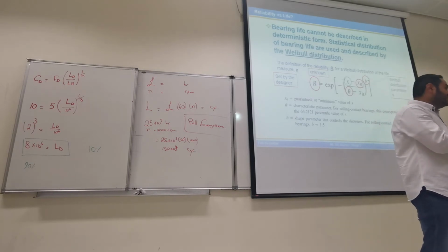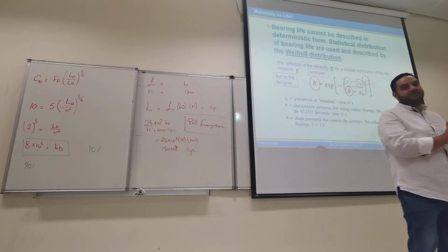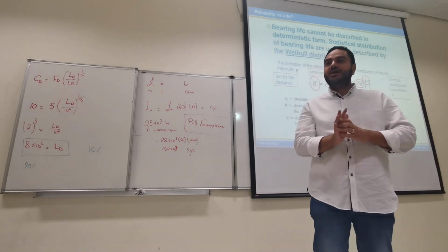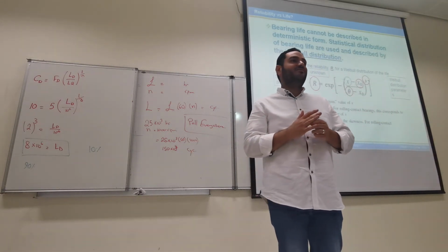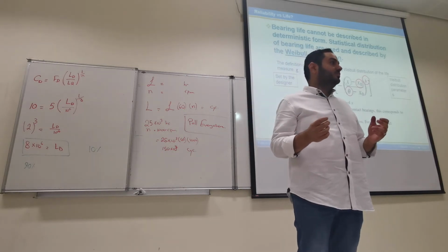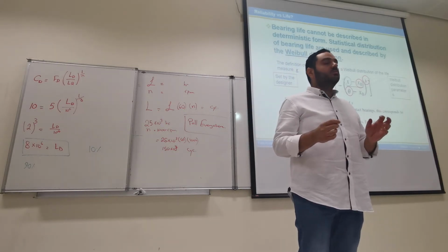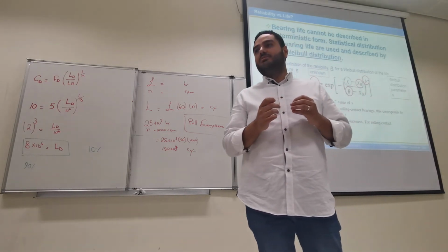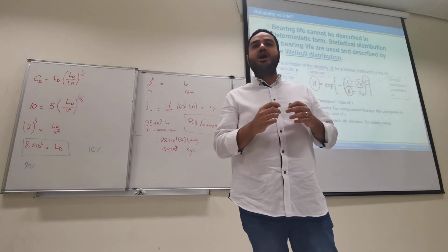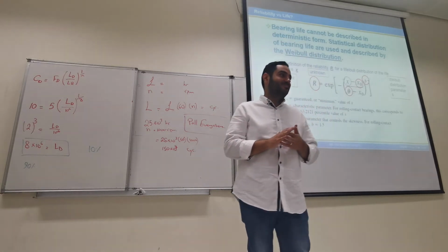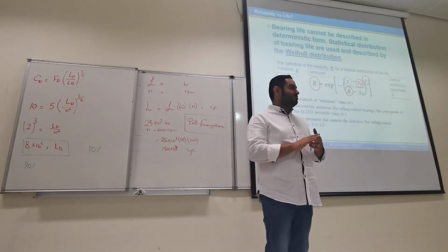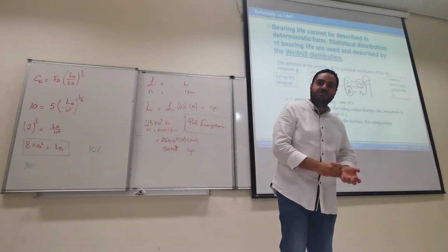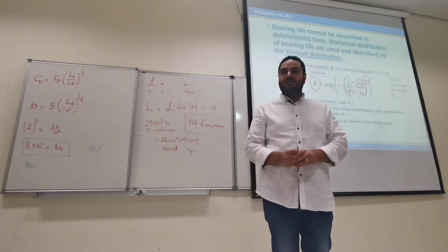How sure are you that this machine will reach these 5 years? That's what we mean by reliability. So you say you design it for 5 years, but it may fail before that. Okay, so now if we consider 90% as a reliability, for example, for cars, it is not considered reliable. It means that from every 100 cars, 10 would fail.